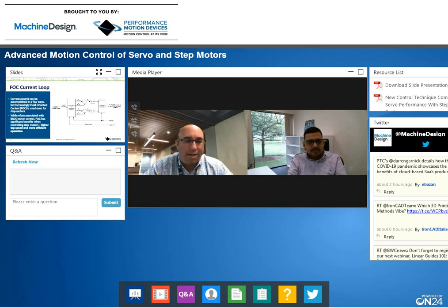And it's trying to keep the relationship between the magnets and where the coil is in this 90 electrical degree relationship so that you have the most optimum way of rotating a motor, not loading the bearings, not bending the shafts, things of that nature. So the FOC does this really cool thing in real time, cycle by cycle, to optimize how you're putting current into a motor and making it both quiet and efficient.